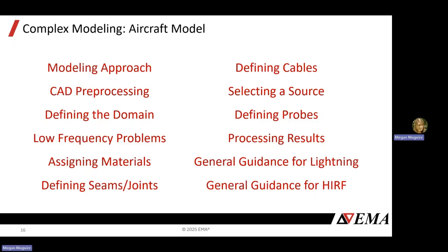And then I'll move into CAD pre-processing. This is your CAD cleaning stage, your geometry simplification. Then defining the domain, so basically what your domain size is, boundary conditions for the domain, things like that. And then I'm going to address some considerations for low frequency problems. And then assigning materials, so what things you want to keep track of for isotropic materials, if you want to include anisotropic materials.